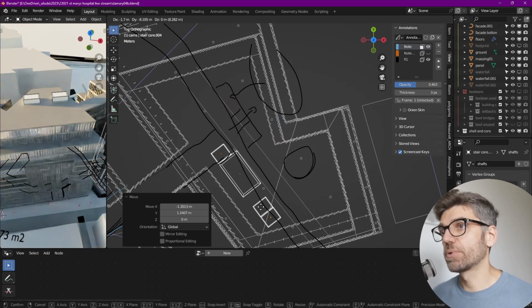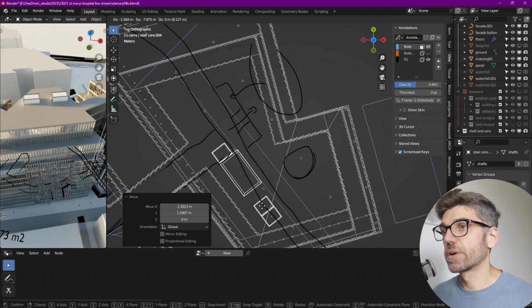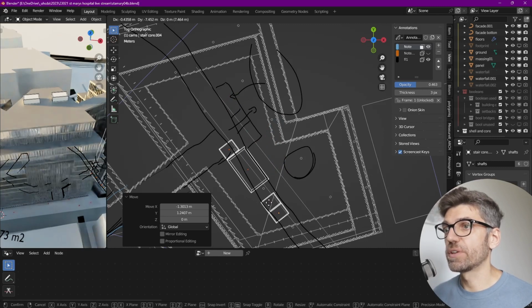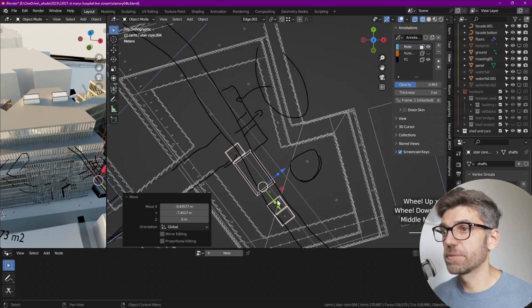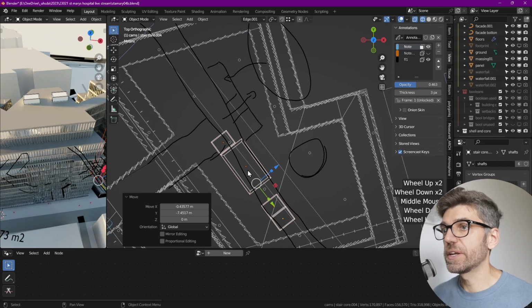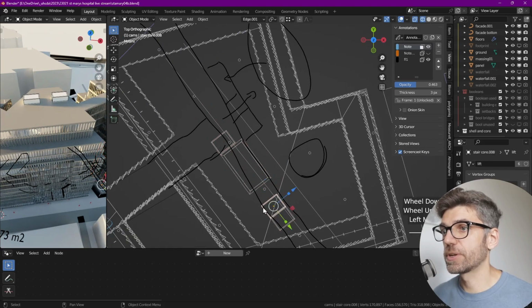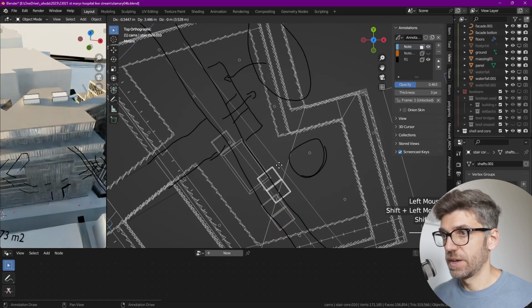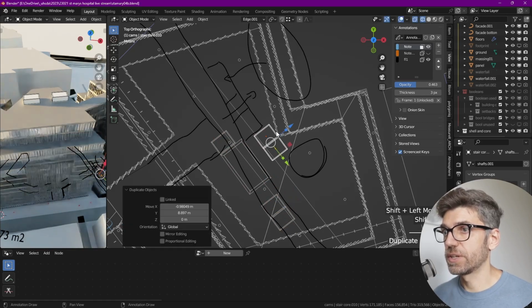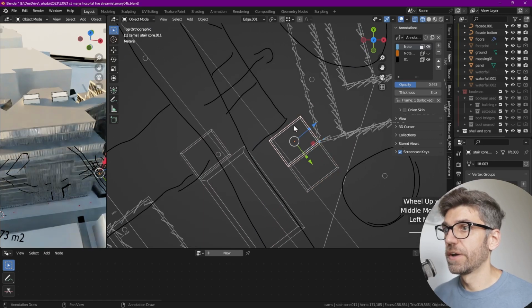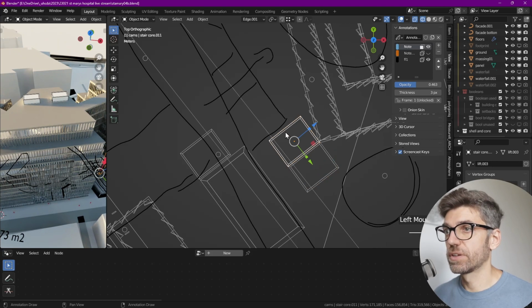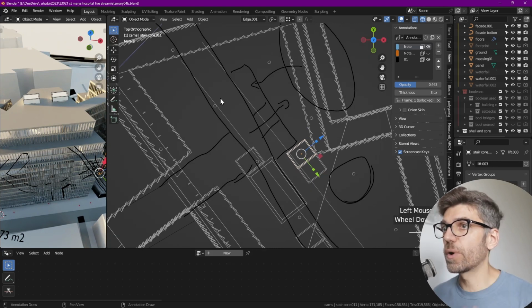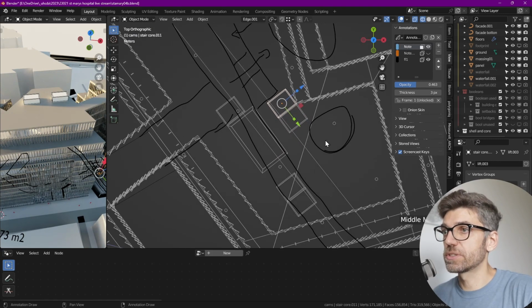So then where else can we put it? We can put the core here, and we might even extend that edge a little bit further out. So then that might make more sense. Or we can have it split, right? So we can have something happening on one side, and then these shafts are coming onto the other side. Now we just have to make sure that, okay, this is shaft and this is lift. Yeah, basically we need to have one shaft that doesn't have any vertical circulation and can service this core, and then the same on this side.